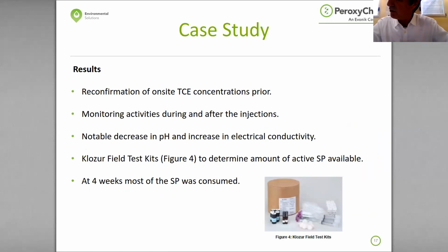Monitoring activities during and after the injections primarily addressed measurements of pH, oxygen, redox, and electrical conductivity. Following the injections with sodium persulfate, there was a notable and expected decrease in pH and an increase in electrical conductivity detected. Contractor used our field test kits.